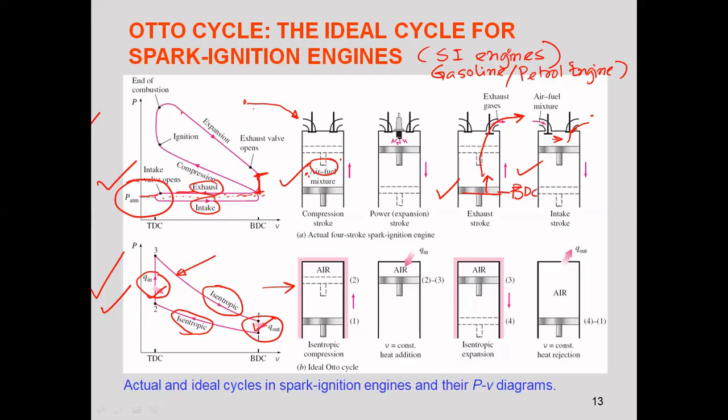Now this will continue because the piston movement continues, and therefore that compression, and the little above atmospheric pressure in the system, continues. Therefore there will always remain a pressure differential between the system and the surroundings, and so there will always be a flow from the system, that is the control volume or the cylinder, to the surroundings through the exhaust manifold. So this will continue at a constant pressure. The constant pressure is due to the piston movement and the flow.